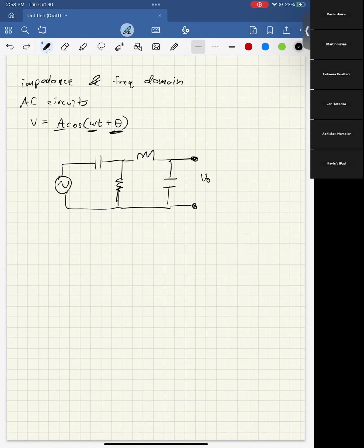If you think about it, a capacitor takes time to charge and discharge. So if we have a sinusoidal coming in, then it'll push some charge in and push some charge out and then push some charge in the other way. And you can represent that as kind of a resistance. And that's what we'll go into here.